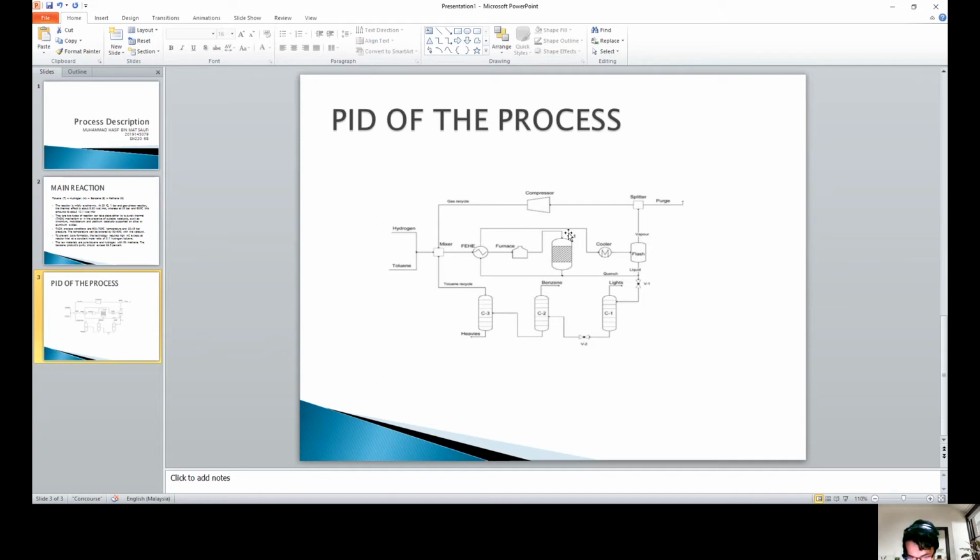For the separation of the liquid mixture, it can equally be done in a sequence of two columns: stabilizer plus benzene top distillation, with side stream for toluene recycling and heavy at the bottom. The presence of two recycles provides an optimum for conversion of toluene. Higher conversion will lower the expense of gas recycling, but will increase the cost of separation because of further byproducts and impurities. In the analysis of optimization, it was found that the optimal conversion is about 70%.